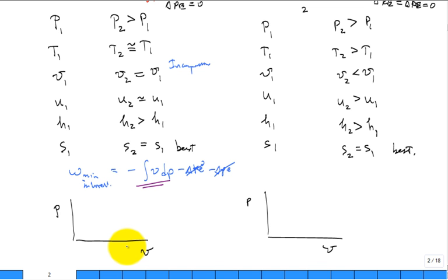Let's somehow locate the same inlet pressure. So the inlet pressure is right here on both of these scales. It's low, isn't that P1? Doesn't P1 low make sense? What about the inlet specific volume to the pump? Compare that to the inlet specific volume of the gas compressor.